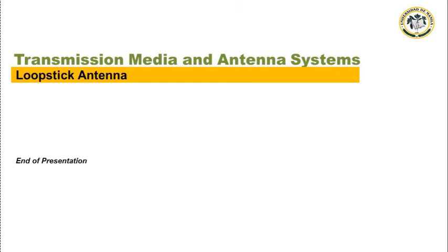Like other forms of loop antennas, loopstick antennas are relatively free from RF noise, as they react to the magnetic portion of the RF energy received, and they are relatively immune to the electrical components, which are prone to noise caused by electrical sources. In small loops, they are very effective receiving antennas, especially at low frequency, where all feasible antennas are small compared to a wavelength.